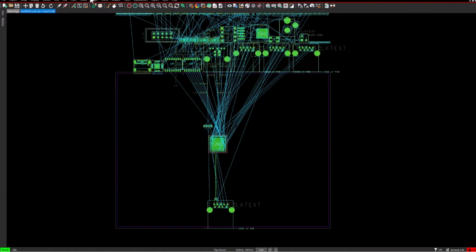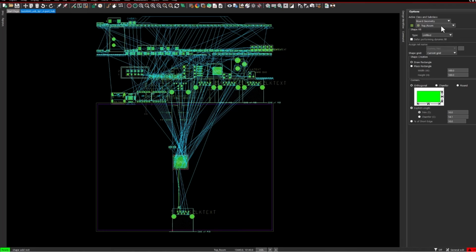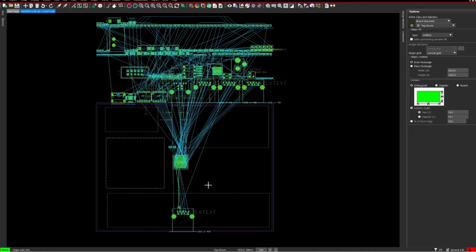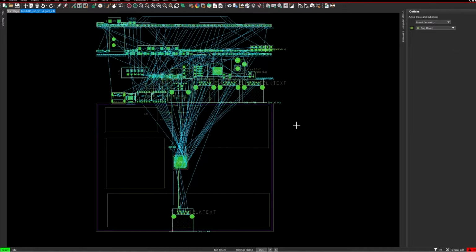Okay, so now that I've figured out my PCB stack up, my impedances, and my constraints, the next step is to figure out the part placement. You would do your visual or graphical planning of where you want to place things based on your customers' needs and requirements, where things need to be positioned. So that's why I talked to mechanical designers and any project stakeholders, and I figured that planning out before I place the first part on the PCB.